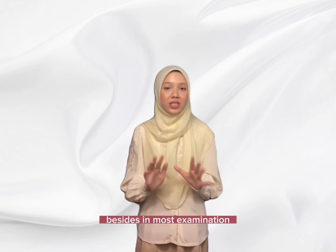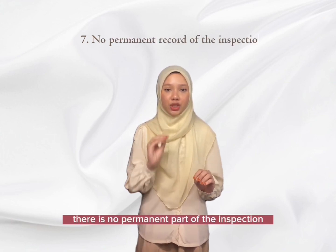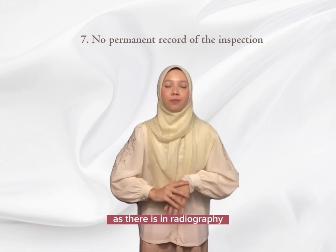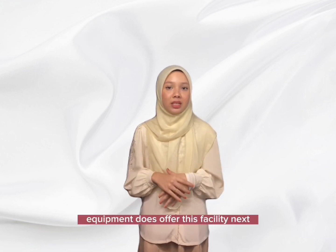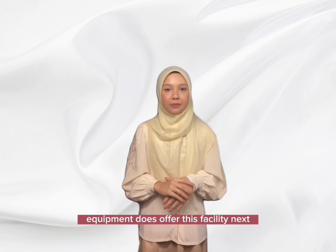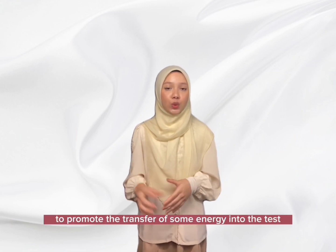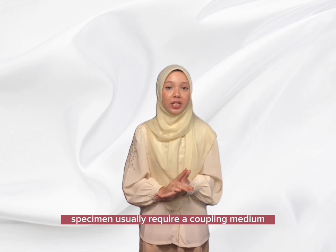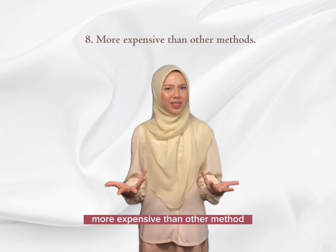Besides, in most examinations, there is no permanent record of the inspection as there is in radiography. However, more recent equipment does offer this facility. Next, to promote the transfer of sound energy into the test specimen usually requires a coupling medium. Ultrasonic testing is also more expensive than other methods.